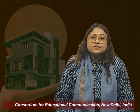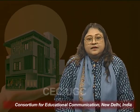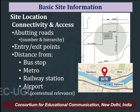It also shows the connectivity and access, how to reach the site. What are the major aspects that will help you to reach the site, what is the connectivity, how you are accessing the site, what are the abutting roads, what is the number of roads, whether the site is a corner plot or a plot embedded deep within a mohalla or a colony. The abutting roads and approach roads also tell you where the site is present. All these come under the basic site information.